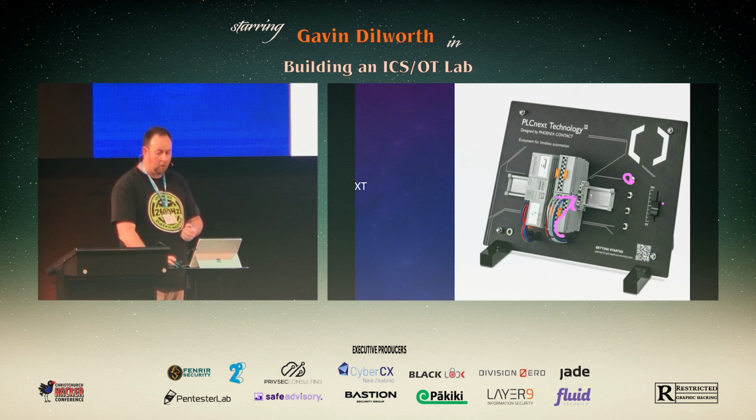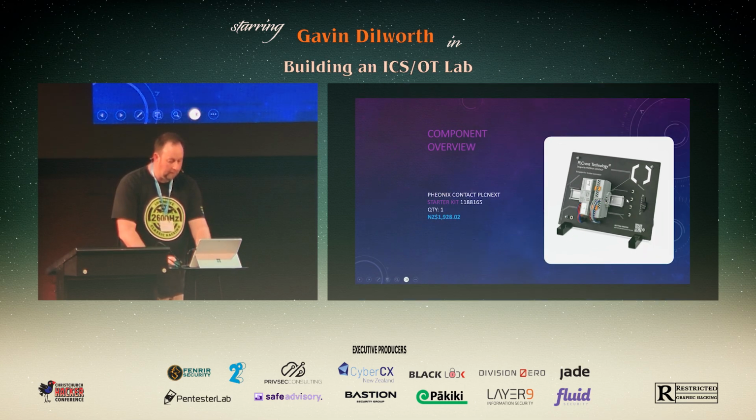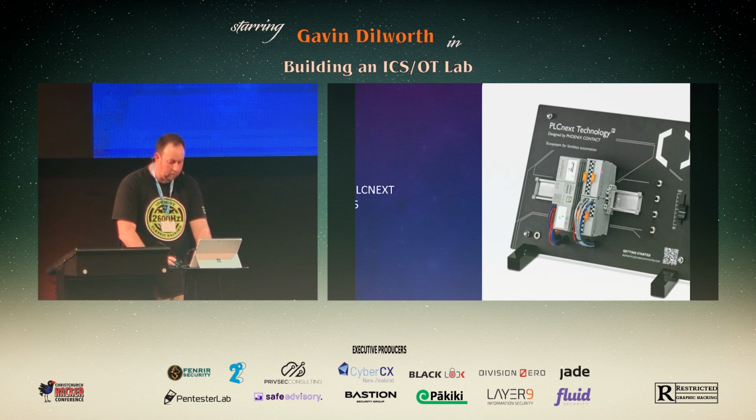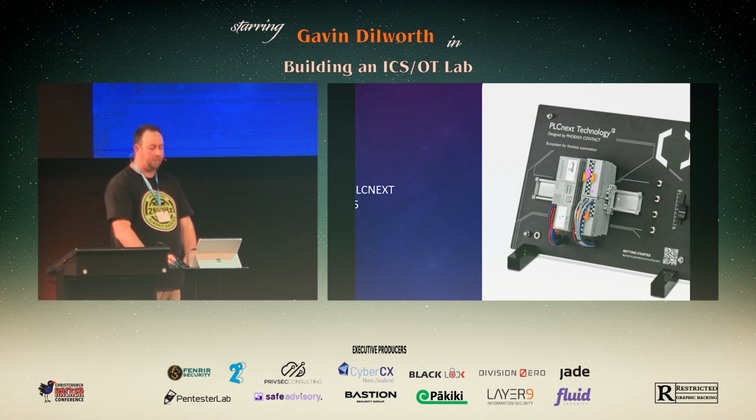You've got an analog input. So this is sliding from 0 volts to 10 volts, and as it slides, it changes its value inside the PLC. Okay, so when selecting cards, there's 4 there. There's slot 1, 2, 3, 4. You can tell by the orange tabs that I've written over.